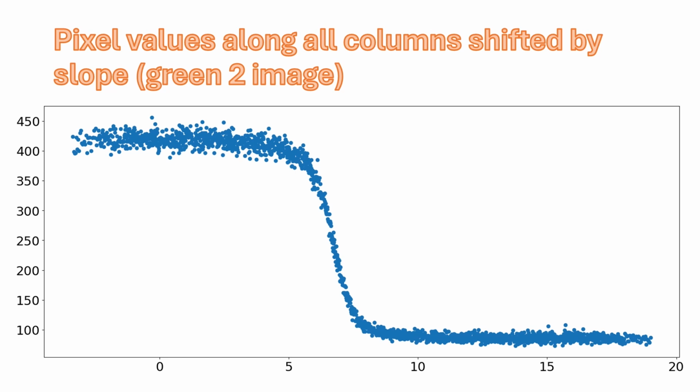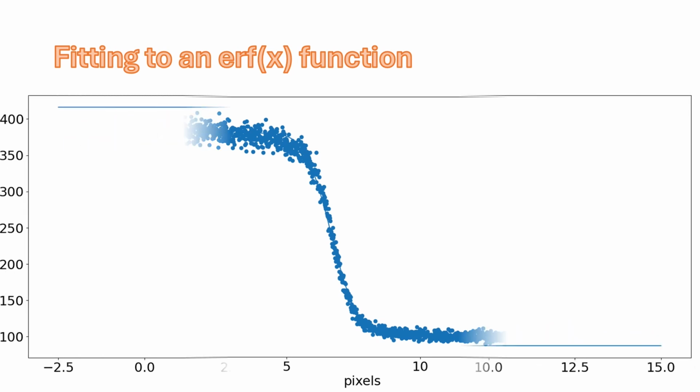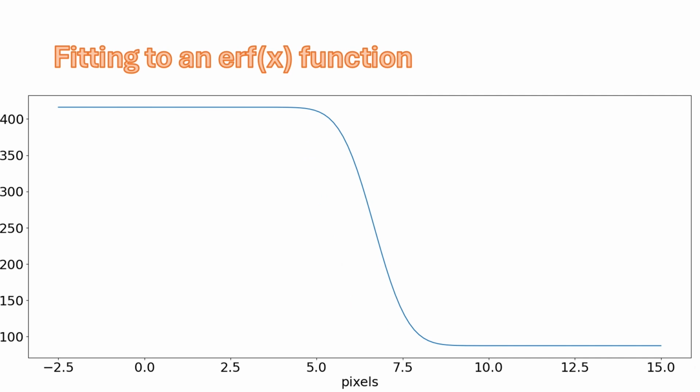So how do we find a smooth plot through here and plot the derivative? There are ways that's done in the standard, and I encourage you to read some of the papers on the standard to figure that out. What I've done in this notebook is to fit the data with an ERF function. So assuming a Gaussian impulse response, we fit with the ERF and plot through there. And then if we take the fitted data, you see that we get a smooth transition as shown here, and then we can use the parameter of the exponential through the ERF to get the MTF.